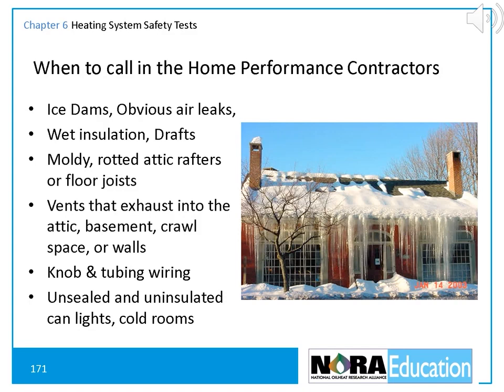When you're visiting your customers' homes, you're going to find conditions where it's clearly important that they call in home performance contractors. Some of these are ice dams, the ice that builds up on the eaves of the house, causing the ceilings to leak and water damage in the home. Obvious big air leaks in the house, wet insulation, drafts in the living area, moldy, rotten attic rafters or floor joists, vents that exhaust into the attic, basement, crawl space, or into the walls, knob and tube wiring, unsealed and uninsulated can lights, and finally, cold rooms.